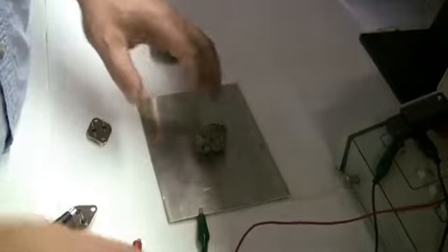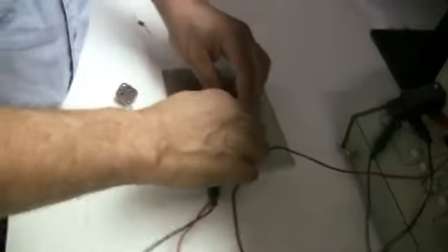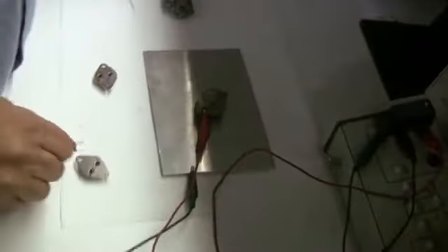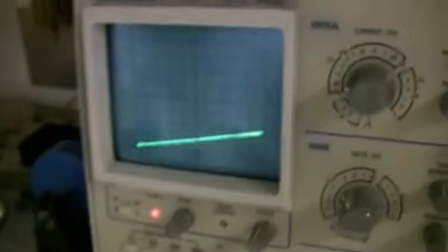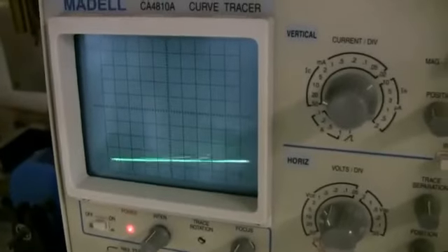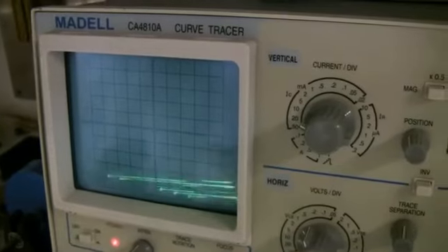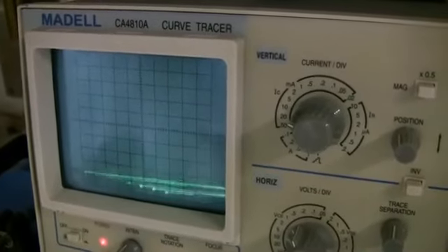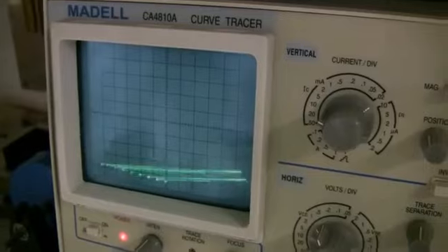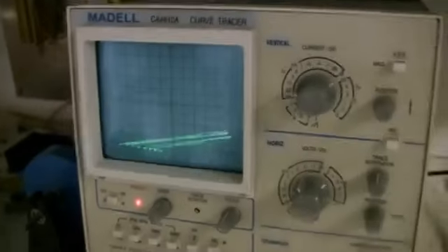And you can see with the rock, we use the aluminum for the emitter, and then we'll just use this for the collector. We use a piece of wire for the base. So you notice right away we have a junction. And see, when we get this where we want it, then we get a transistor, more in the high frequency end here.